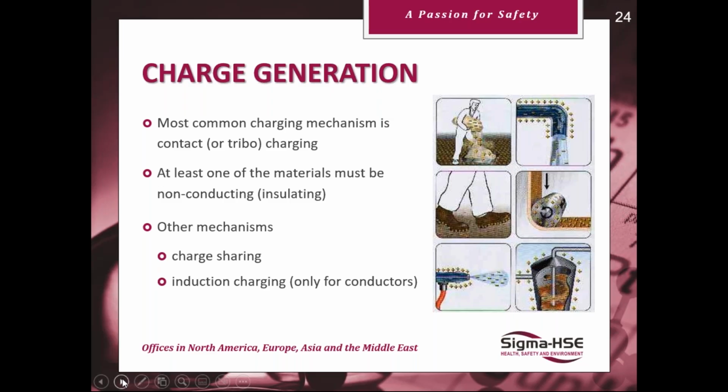So the most common charging mechanism is contact or tribocharging. This is the most common you get, where something contacts together, or they're different parts of the triboelectric series, where the further away they are on this series, the more risk you have of charge generation occurring.